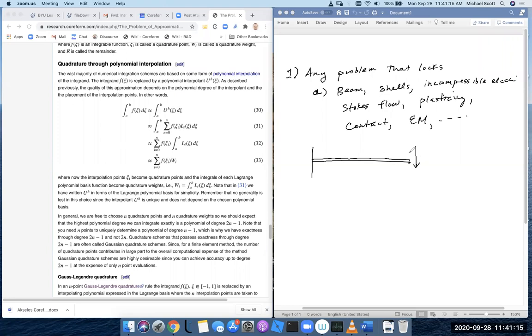So let's say you had a beam bending problem and you knew the exact solution was 1. Let's say U exact was 1, but when you discretize it into elements and you solve the problem, maybe you get a displacement of 0.000001, something like that. What we say is that it's locking because you can see it's locked up, right? It's not moving.